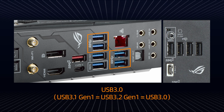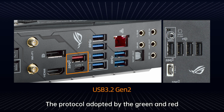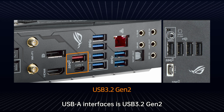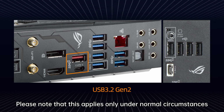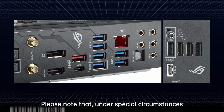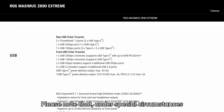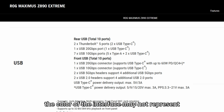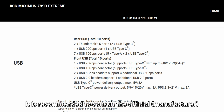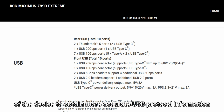The protocol adopted by the green and red USB-A interfaces is USB 3.2 Gen 2. Please note that this applies only under normal circumstances and when the USB logo SS10 is marked on the interface. Please note that, under special circumstances, the color of the interface may not represent the protocol specifications. It is recommended to consult the official manufacturer of the device to obtain more accurate USB protocol information.